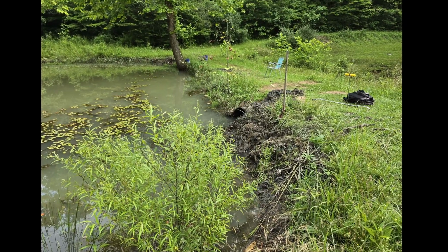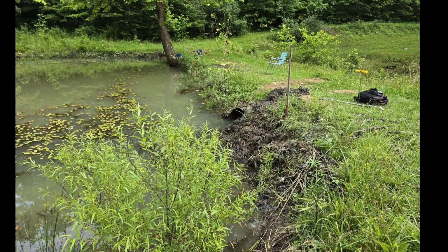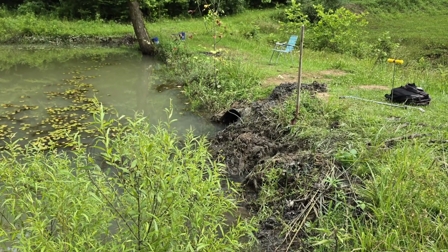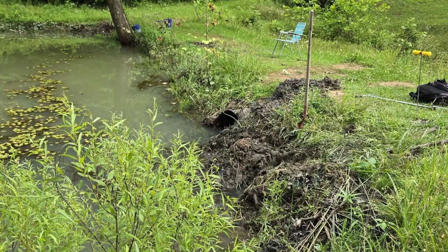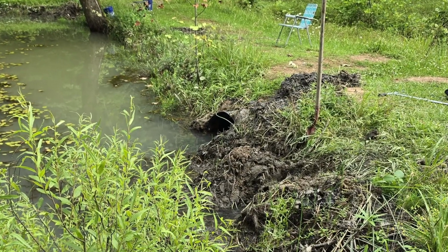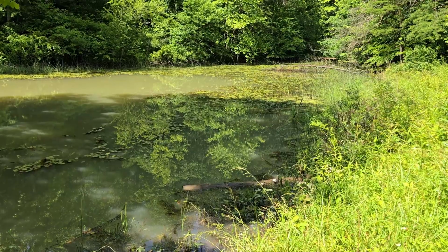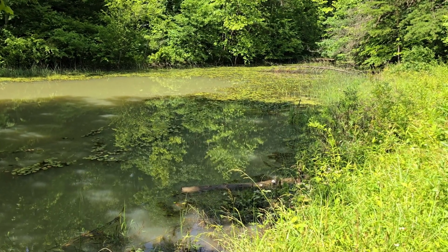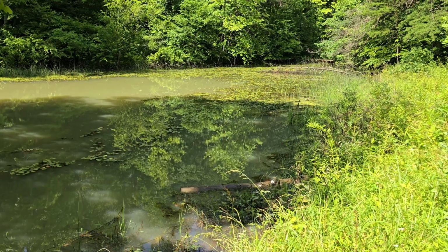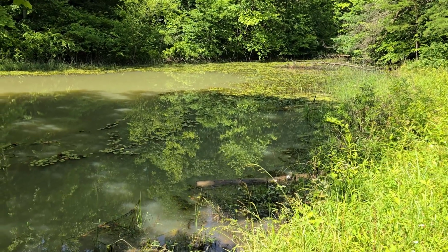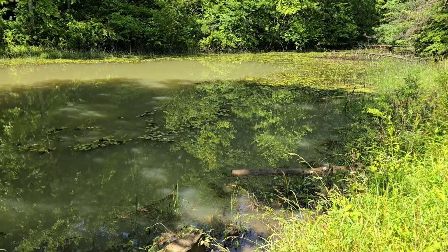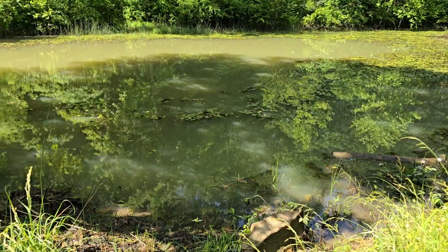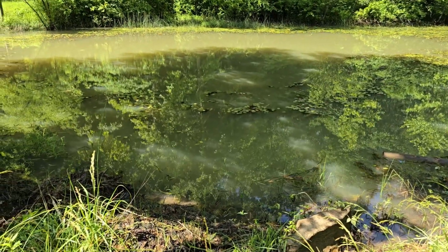I observed a 24-inch diameter plastic overflow pipe whose entrance had been blocked halfway by beaver. I could not believe that beavers were living in this small pond that's located in the mountains and in the forest. DJ showed me where 2 additional overflow pipes had been installed in the dam. I would not have been able to find these pipes without his help. The entrance to one of these pipes was completely buried and blocked by beaver, while the entrance to the other pipe had been dug out, possibly by a beaver using it as a bank den.